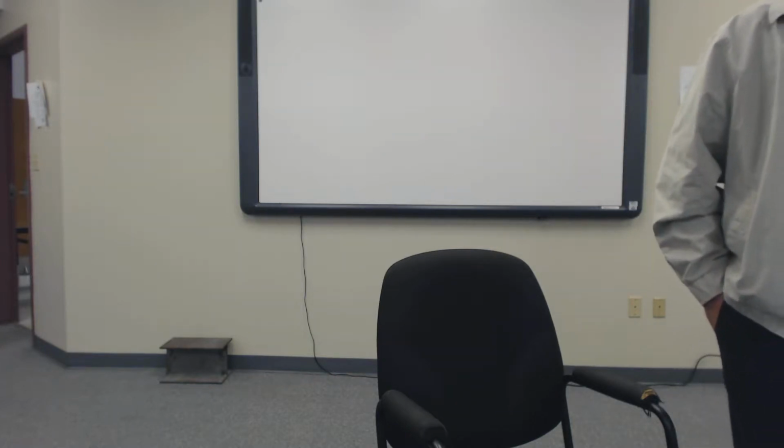I know over in Bay St. Louis, I did a job. They had to be up at an 18-foot clearance level. So that post had to be 18 foot tall. So I had to put it 6 feet in the ground, which means I had to get a 24-foot post. Okay? So you can see that depending on what type of system you're dealing with and where you're dealing with, will depend on what system you go with. Now, there's some areas where you have to go with piles.